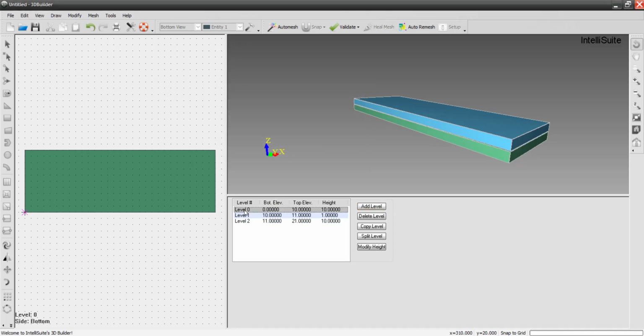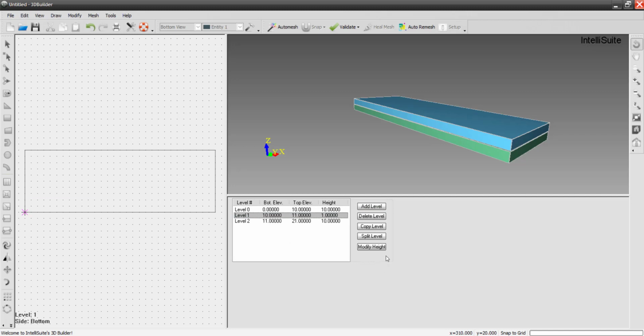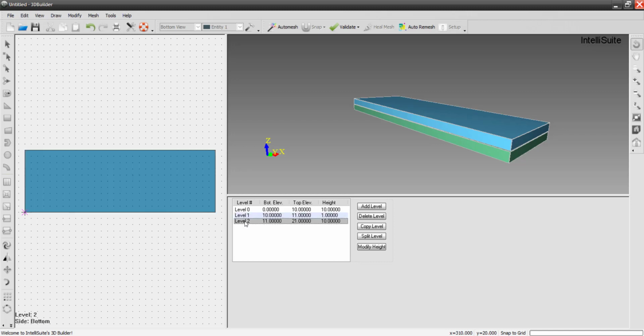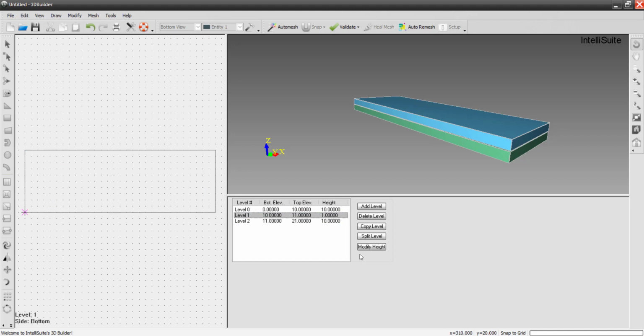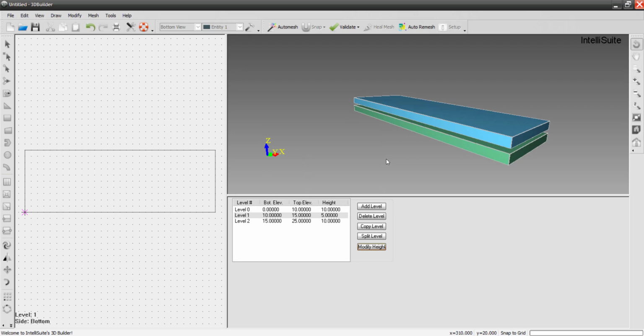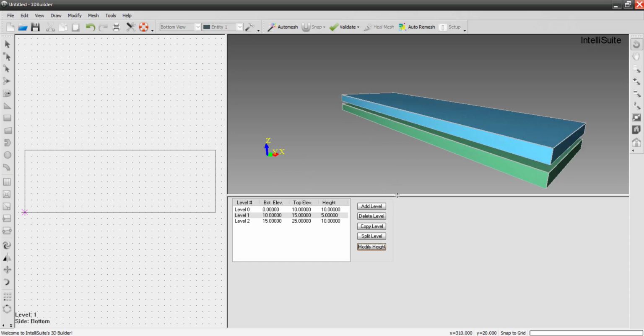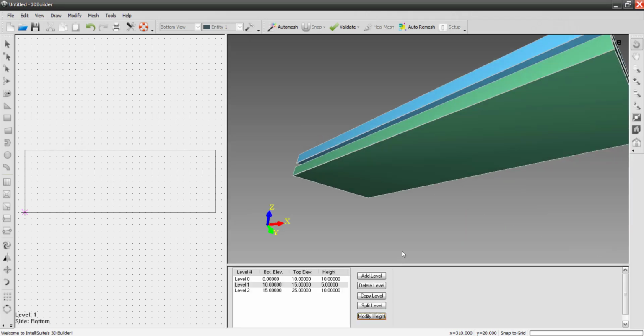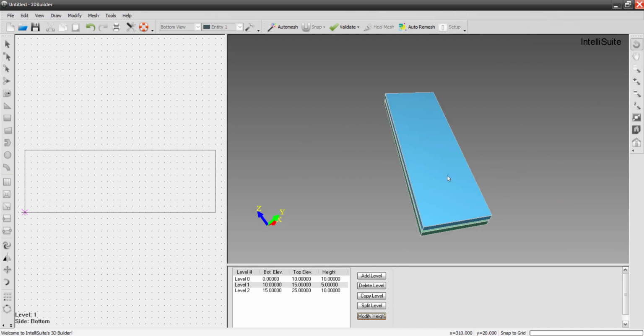So we click OK. So that is a blank layer. Selecting the blank layer, now layer 2 has got shifted. So we modify its height and we maintain it at 5 micrometers. Okay, so this is what we do. Now we see a gap between the two.